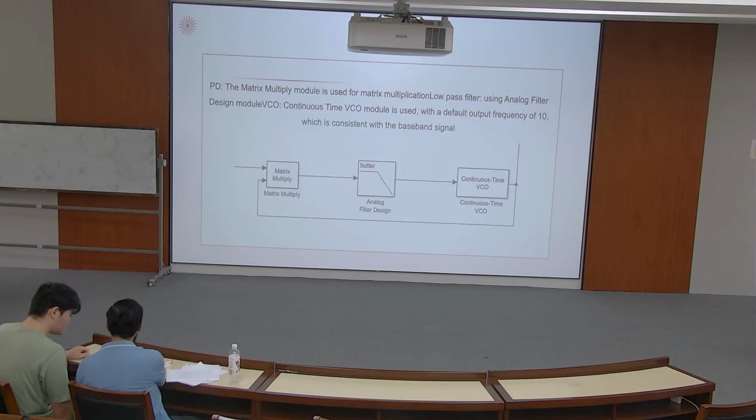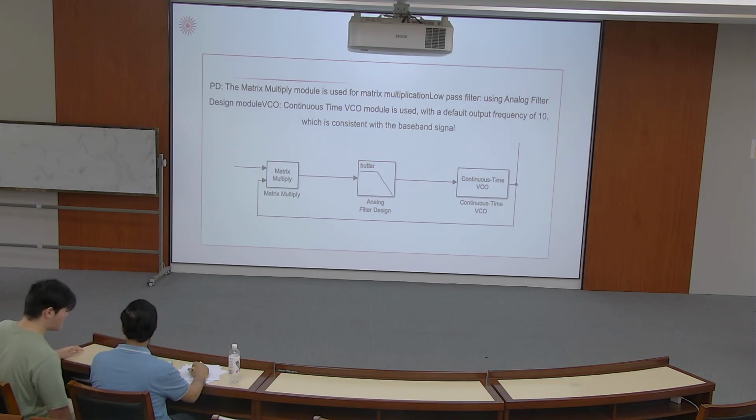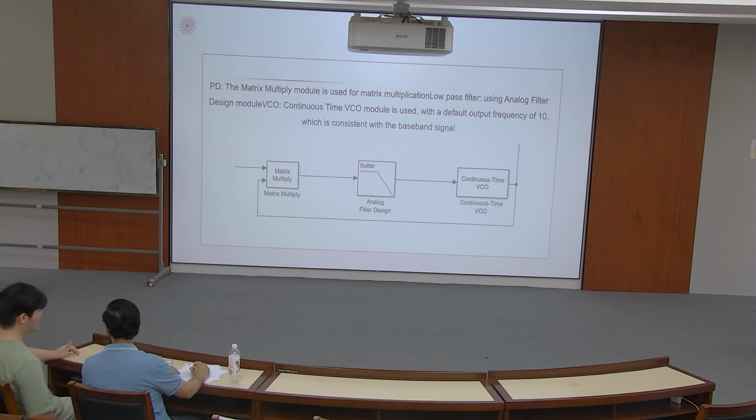Simulation of FM demodulation. We built a PLL demodulation model in Simulink. We use the matrix multiply block as the phase detector, analog filter design as the low-pass filter, and the continuous-time VCO as the oscillator.